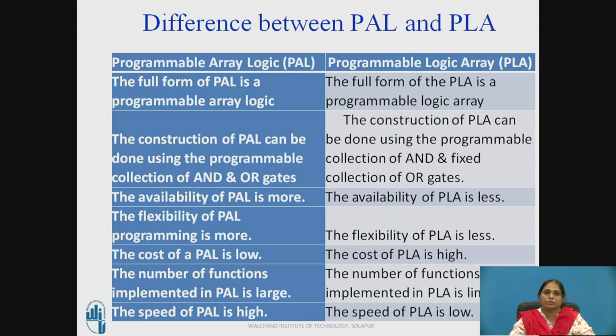Next we'll move on to the difference between PAL and PLA. PAL stands for programmable array logic, and PLA stands for programmable logic arrays. The construction of PAL can be done using programmable collections of AND gates and fixed OR gates, as we discussed. The construction of PLA can be done using programmable collections of both AND and OR gates. The availability of PAL is more, while the availability of PLA is less.